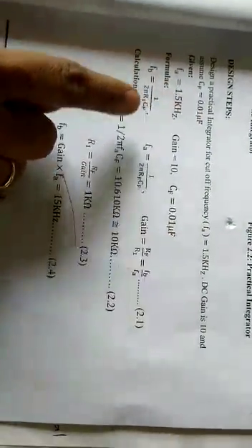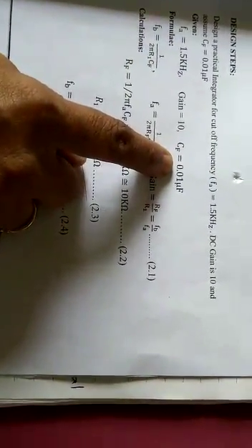So using this data, we know the integrator formula for the cutoff frequency FA and FB. We know the gain formula. So in this, if you substitute FA equal to 1.5K and CF equal to 0.01, we obtain RF equal to 10 kilo-ohm. Similarly, we will get the R1 value equal to 1K. So with these design values, we are building a practical integrator.